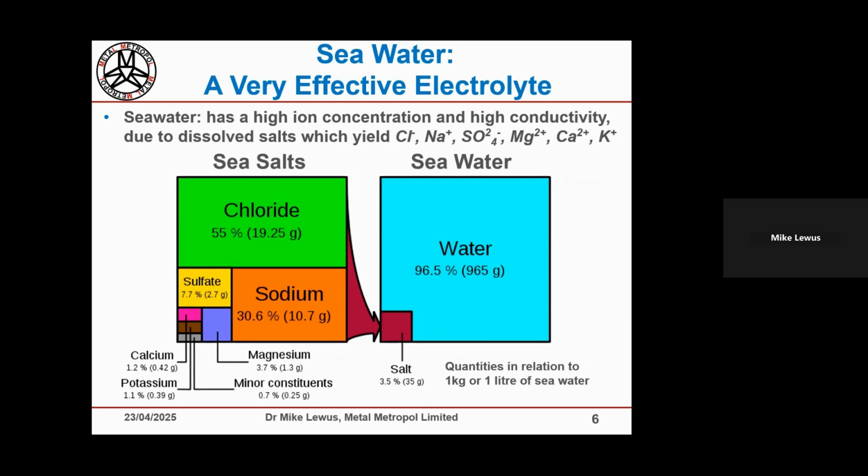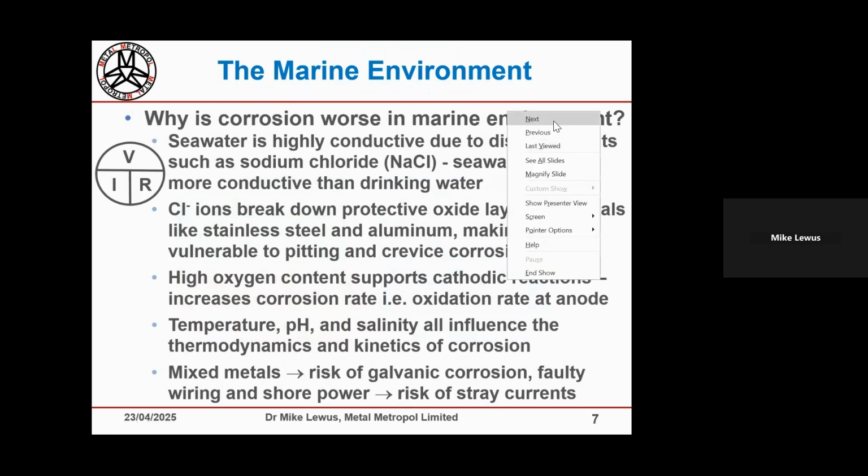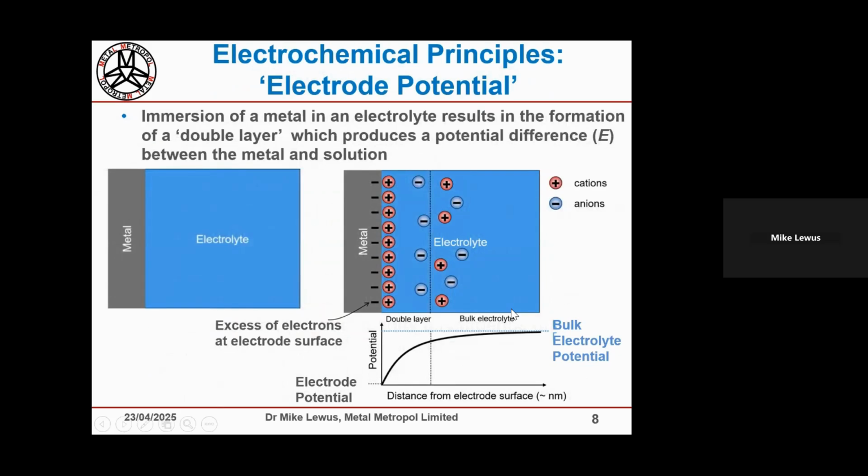Now, to put it in perspective, 316 stainless steel, which most people would consider extremely corrosion resistant, is only recommended for use up to 1,000 to 3,000 ppm chloride, and we've already got 35,000 ppm. So it paints a quite ghastly picture, but because we know a lot about the things that are driving corrosion, we can do many things to protect ourselves.